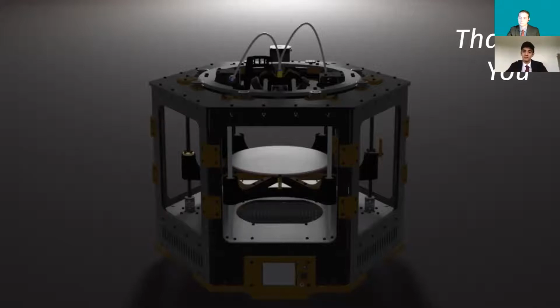So the next step is to get it medically accredited with medical tests on the stent materials, such as TPU. And for that, we'll be conducting biocompatibility tests, as I said, on fibroblast cells to get a growth model, and then human epithelial cells for realistic conditions. And then the next thing we'd want to do is increase the print materials from thermoplastic polyurethane to multiple print materials so we can introduce stents for multiple arteries in the body. And also, we would like to utilize the existing dual extrusion hardware for more complicated stent designs that could help, for example, be drug-eluting stents.